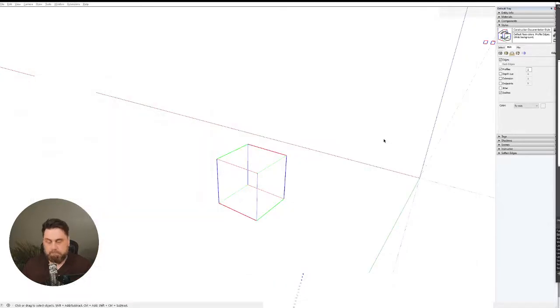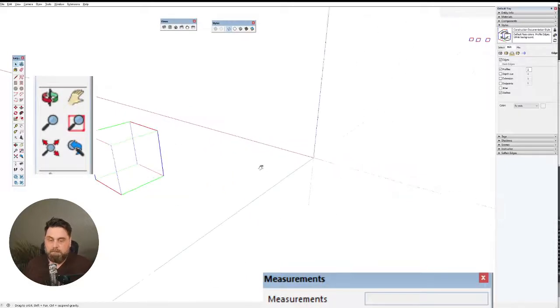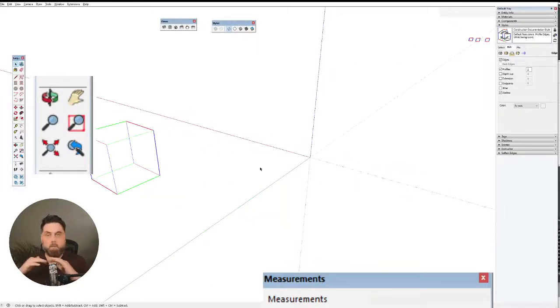So in SketchUp, we have these axis lines which give us the indicators of us being square. You have basically your model axis, which is the world axis. It's square in the model itself, and that's this set of axis lines here. These don't show up in anything. They don't show up in your renders. They don't show up when you export a SketchUp screenshot or anything like that. They're strictly there to help us as modeling tools.